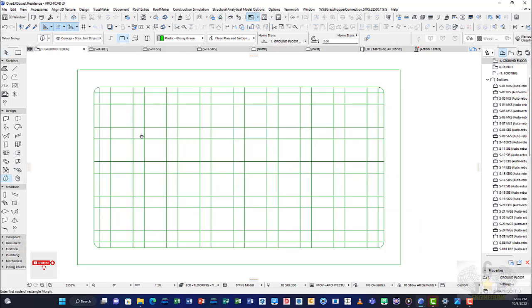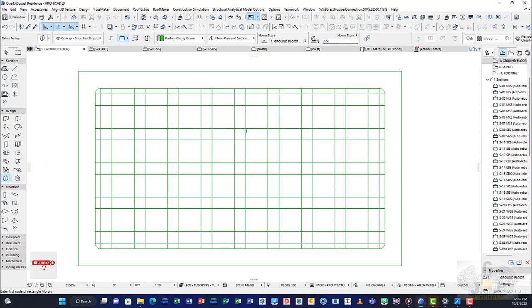The second way to do it is that you have to hover over your geometry, your sketch closed shape. Once you're there, you press down the space bar. When you press it down, you can see what happens, right? It highlights my sketch. It recognizes that this is a closed profile. So from this closed profile, because you have activated the morph tool, you are able to create a profile here. This is the second case.